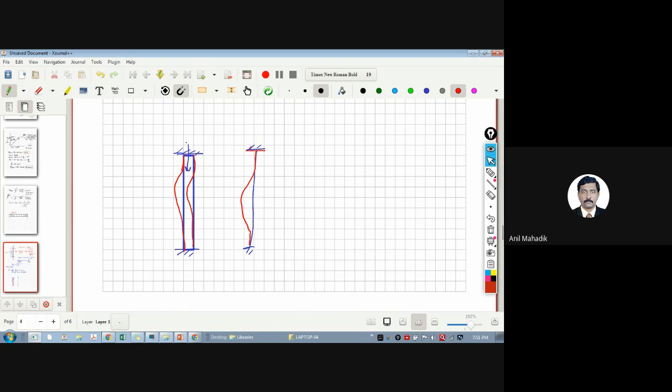The buckling or bending starts from this point, and again it starts till this point. So the bending is between these 2 points only. Within this range, it is not buckling. So whatever this length is, we call it L effective. And this is the total length of the member. This is a 2D diagram, a single line diagram.